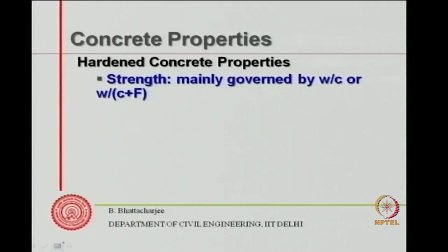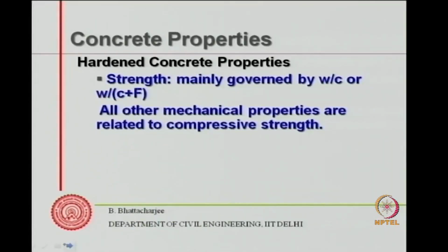Strength is mainly governed by water cement ratio, or water to cement and fly ash ratio. All other properties can be related to compressive strength. I mean all other mechanical properties.